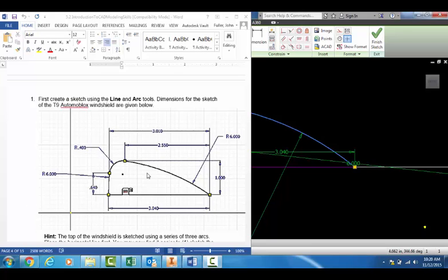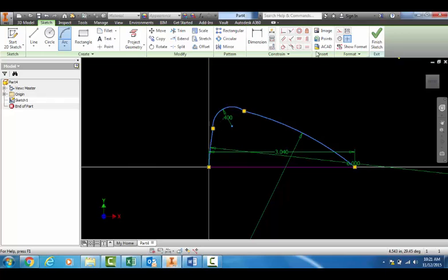All right, so let's come back to our assignment now. We have to add some dimensions in. Notice from this point to this point, we have a length of 3.01 inches, and from this point to this point, we have a length of 2.55 inches. And then finally, from this point to this point, we have a height of 0.64 inches. So let's put those dimensions in now. Let's come back to our assignment, hit dimension. So let's go from here, click on that point to that point. Okay.